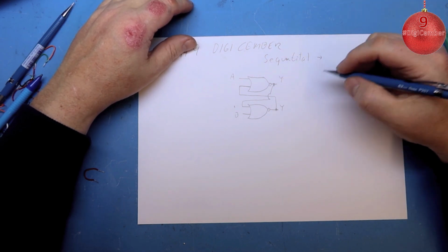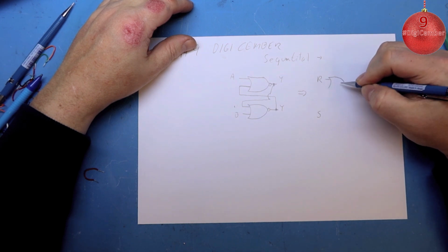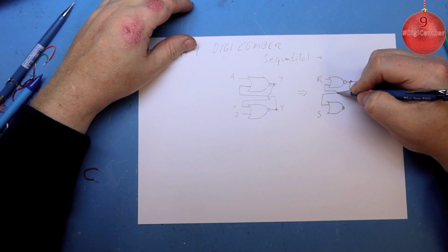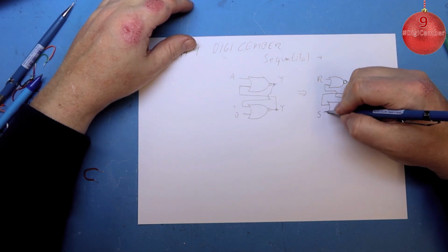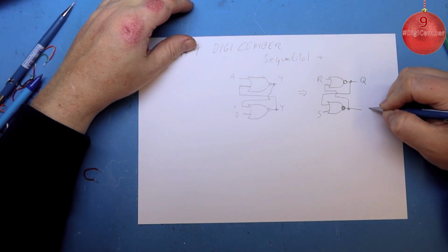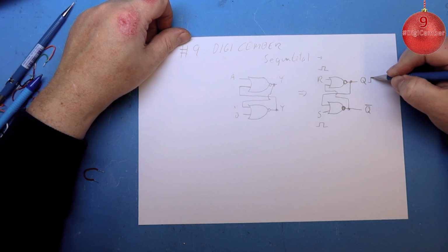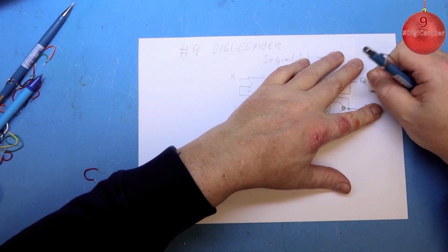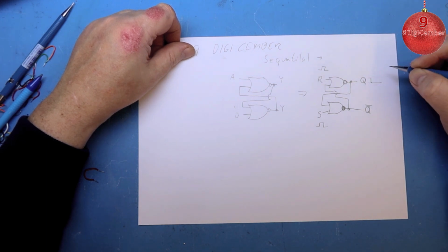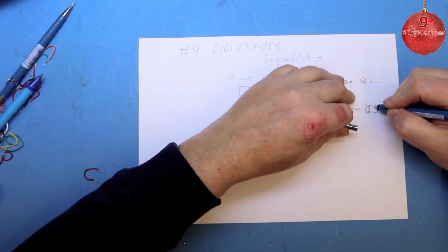Normally on this kind of gate, we name the inputs a bit differently. Namely, we call them R and S, like so. And we draw the gates like so. This is an open ring, not a closed one like that. I call these R and S for reset and set. And then I'm going to call these Q and not Q, or Q inverted. And the theory is that when this gate is going like so, actually this is wrong. If I take this the right way, when I do the reset, this will go low and stay low, and on this one it will go high, and they will of course follow the same time pattern.